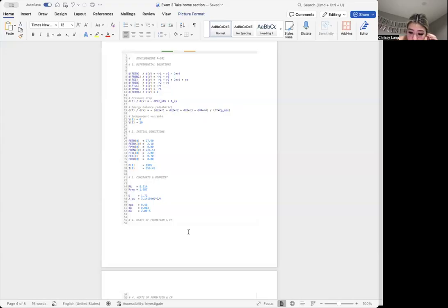At the inlet, V equals 0, I used the flow rate, temperature, and pressure given in the stream tables for R301. All components listed in the stream table were included in the model, even the inert or non-reactive ones, so the total flow and heat capacities were consistent with the real process. Once the system was set up, with an equation for each of the species, plus 1 for T and 1 for P, I ran Polymath over the corresponding reactor volume or catalyst weight.